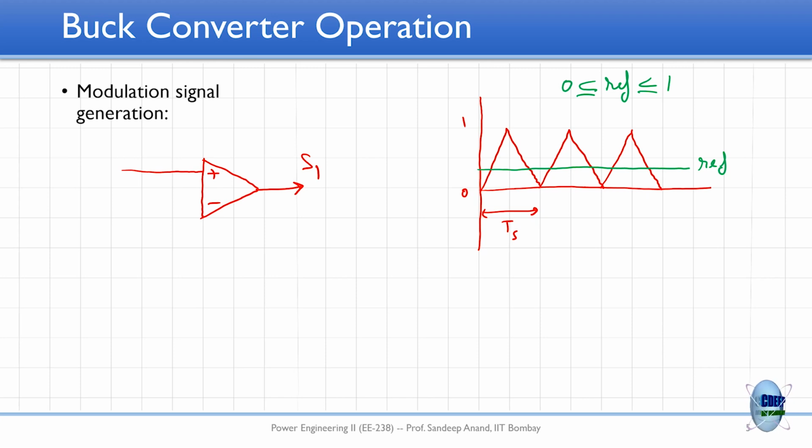And you put this reference signal and this triangular signal and put it in a comparator, alright.